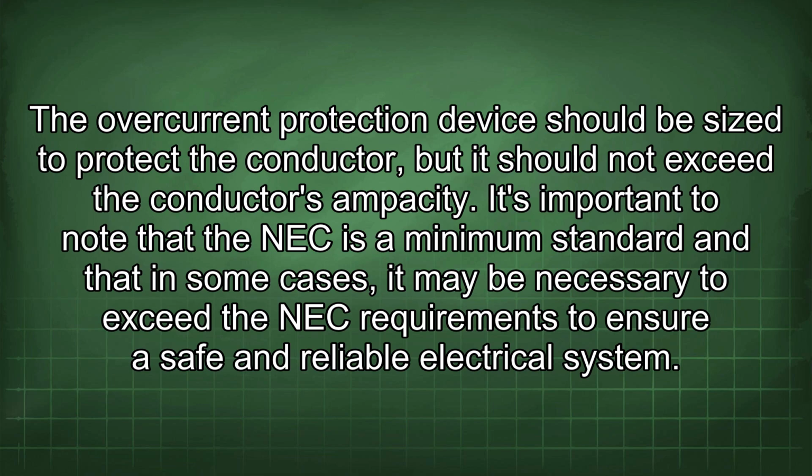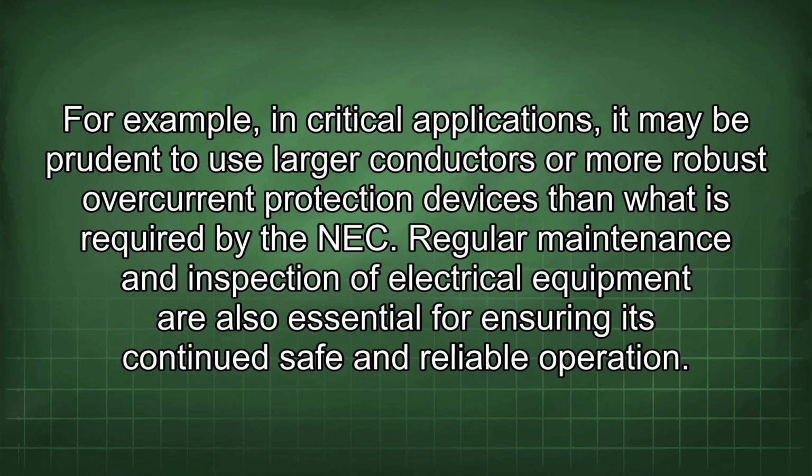It's important to note that the NEC is a minimum standard and that, in some cases, it may be necessary to exceed the NEC requirements to ensure a safe and reliable electrical system. For example, in critical applications, it may be prudent to use larger conductors or more robust overcurrent protection devices than what is required by the NEC.